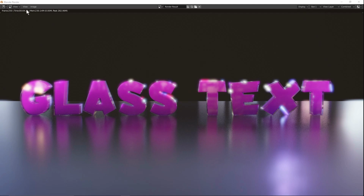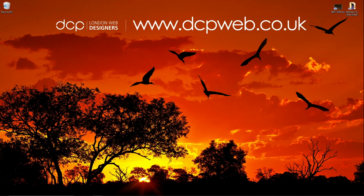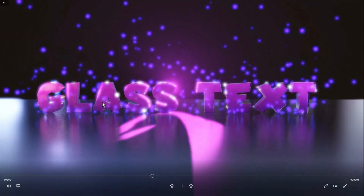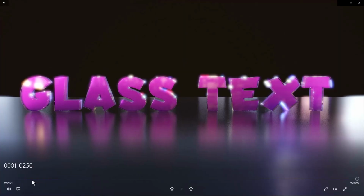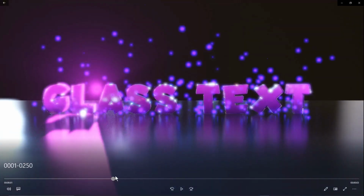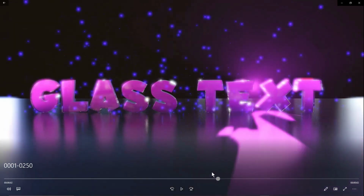Okay, so Blender's finished rendering out all of the frames. We're on frame 250, you see here. We'll go to File, Save As, or just Save. We'll minimize this and see what the final render looks like. We'll open that up, and here we can see the light flowing across with the particles coming up. And if we do this a bit slower, let's scrub across it. We'll also see the HDRI lighting. You can see around the edges here how it's affecting the bloom and the glow and all that good stuff.